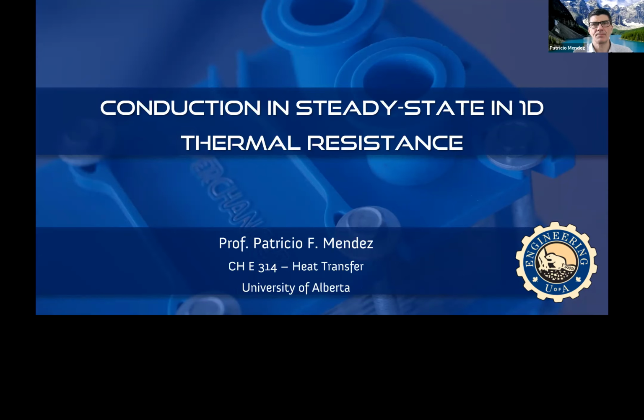And we saw that this energy balance, we could do it as a batch between two time intervals or as a rate. We also saw that this equation we wrote, that is a very universal equation, makes sense only when we have made a control volume and we have determined clearly what the boundaries of that control volume are.